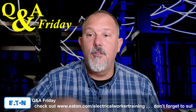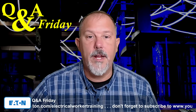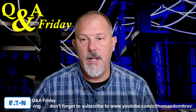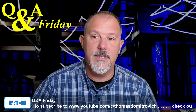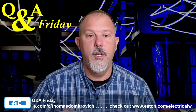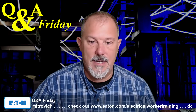We say now GFCI protection shall be provided for the branch circuit or outlet supplying the following appliances rated 150 volts or less to ground and 60 amps or less, single or three phase. Automotive vacuum machines, drinking water coolers, cord and plug connected high pressure, tire inflation, vending, etc.